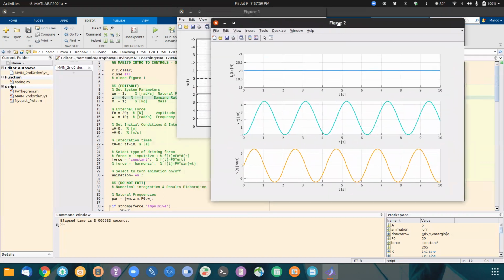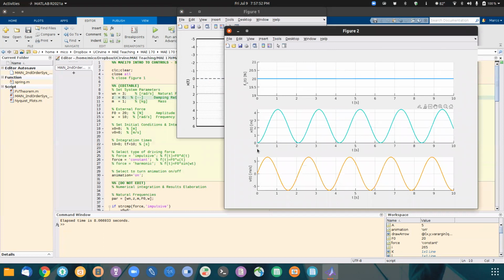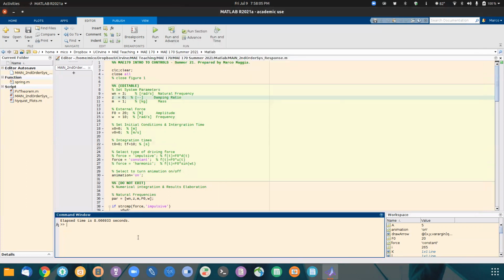If you go back to the notes, you'll see that what we considered was the oscillation between 0 and 2. So why is this maximum not 2? Well, that is because it was just a particular system. Here we're using different numbers. How do you find the maximum? Well, for the undamped system, the maximum is 2 times f naught divided by omega n squared.